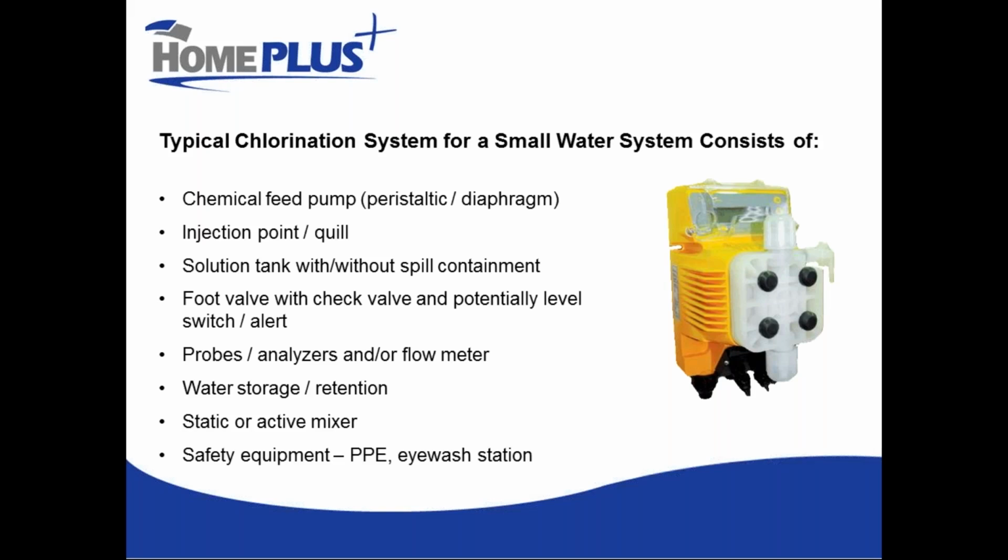There's a solution tank that holds your chlorine solution. Often that'll have some sort of spill containment around it. We have a foot valve inside the solution tank. That's the point at which the chlorine is actually sucked up. It'll usually have a little screen on it to keep debris from getting sucked in there as well. It'll be lifted a few inches off the bottom of the solution tank, again, to prevent sucking debris off the bottom of the tank. And it will also have a check valve in it to ensure that your pump does not lose prime when it stops pumping.